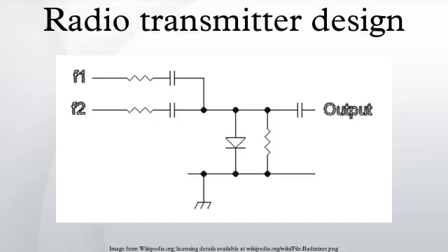The frequency of the oscillator is then multiplied up using a frequency multiplier stage, or is translated upwards using a mixing stage, to the output frequency of the transmitter. The amount of modulation is referred to as the deviation, being the amount that the frequency of the carrier instantaneously deviates from the center carrier frequency.